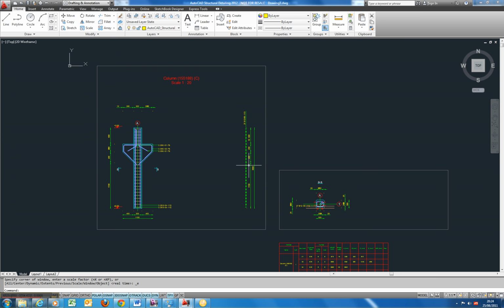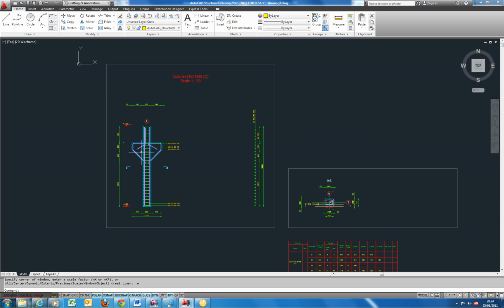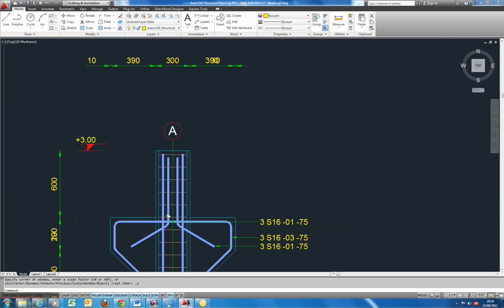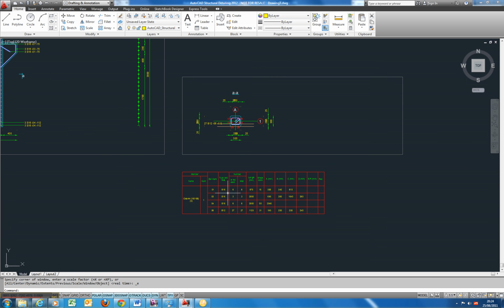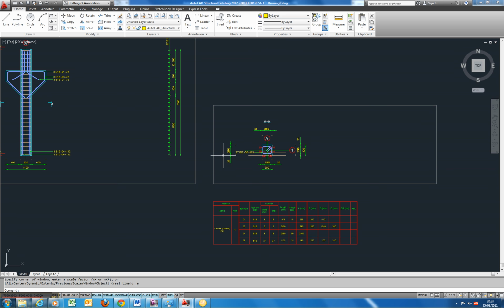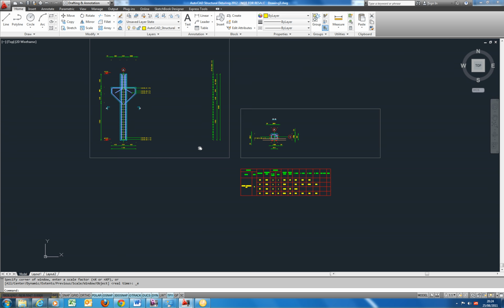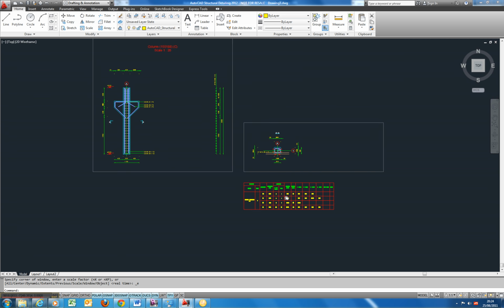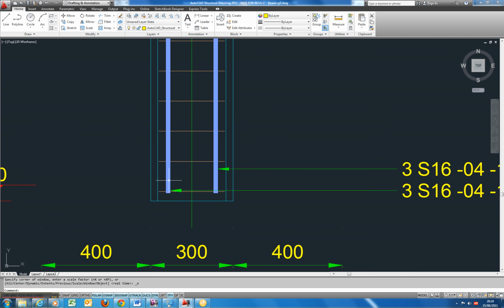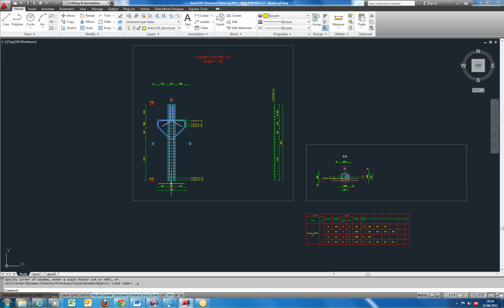Okay, that's it calculated there. You can see it's done the full arrangement plan. It's got my bar schedule. It's got my section details in there to the standard I actually want, and I'm ready to change that information. Again, all this can be uploaded and changed as well. So if I change any of the bars, now it's in an ASD format, this will update the schedule.